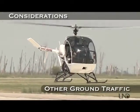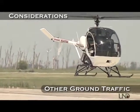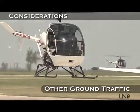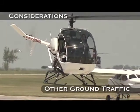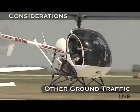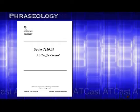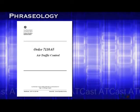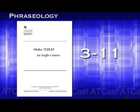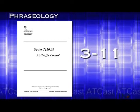Finally, be aware of where ground traffic is in relation to helicopters. Pilots of fixed-wing aircraft might not be aware of helicopters operating nearby, especially if the helicopters are above them, such as when air taxiing. Issue traffic advisories as necessary. Let's take a look at the phraseology you'll need to know. Rules governing ground movement of helicopters can be found in the 7110.65, Chapter 3, Section 11.